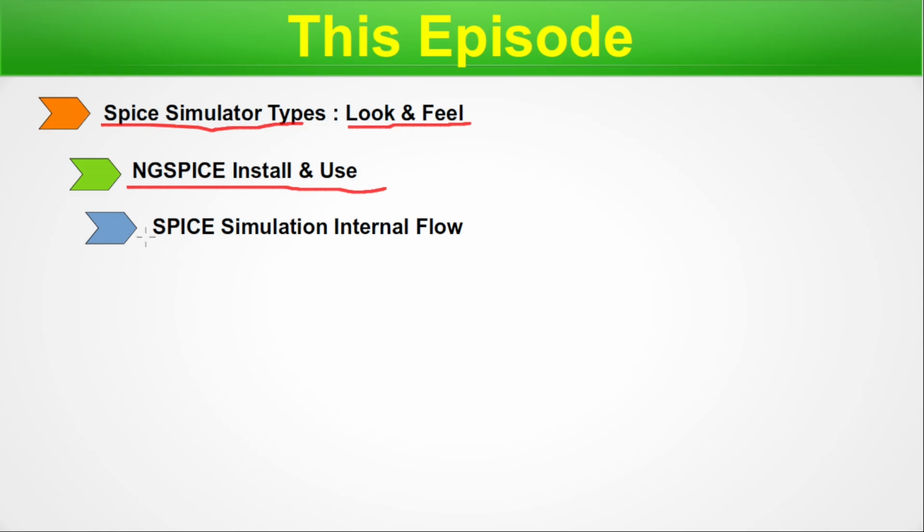Next, we will talk about the internal flowchart or the process flow of the SPICE simulator. This is a generic one and this could be applied to any of the educational as well as the industrial SPICE tools. However, there will be some additional steps in case of an industrial SPICE tool that is specific to a particular EDA vendor, and hence we will not be able to give you the minute details of such industrial SPICE tool substeps.